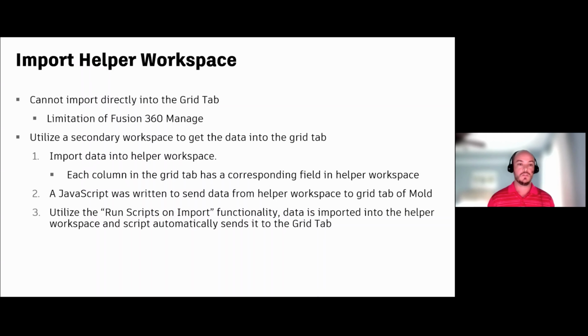Anybody who uses Fusion 360 Manage knows that you cannot import directly into the grid tab. So what we did to overcome this was to build a helper workspace. And this helper workspace is exactly that. It's a new workspace where there are fields within the item details that correspond to every column in that grid tab. As a user imports the data into this helper workspace, a JavaScript was written that then takes that data and transfers it over into the mold and project tracking record.